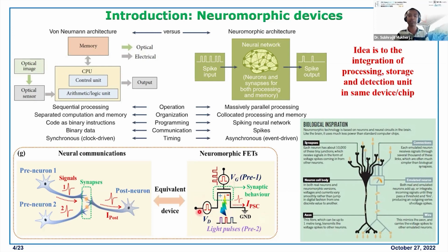Let's say it's a 3-terminal device. In source and drain, you have signals to read at the output, and the gate terminal is your control terminal. By this way, you can write or control your devices. Also, as this type of device is generally optically active, light can be used as a virtual gate or floating gate to control the device further, so you have more selectivity on the output.